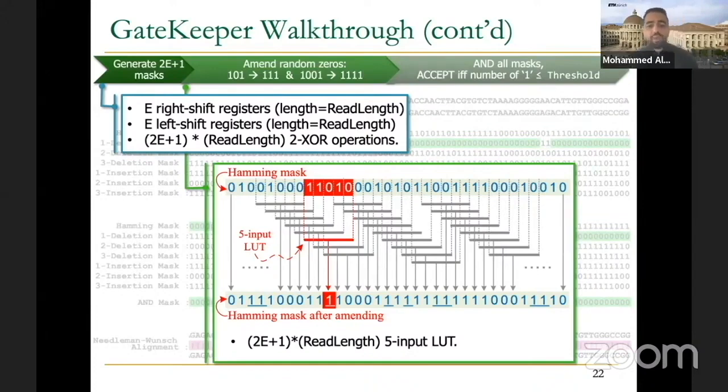For us, we were aiming to change only a single zero or two zeros. So how many inputs do we need for that lookup table? This is a very important metric to choose the appropriate FPGA so that we don't double the resource utilization. If the number of inputs for the lookup table is less than or equal to the number you have in the FPGA, then that is the ideal utilization of the FPGA resources. If you have more than that, you directly double the number of lookup tables, even if they are underutilized. So how many inputs do we need? This is the important question now.